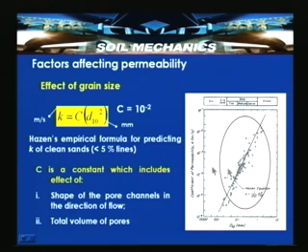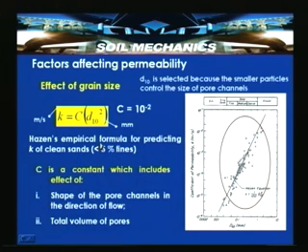So, that is the reason why it is said that it is valid for sandy soils. And another question is why the D10 is only selected. The D10 is selected because the smaller particles control the size of the pore channels. Suppose there are large particles; there is a chance that the large pore spaces can be filled with small particles, and then the pore space can be reduced.